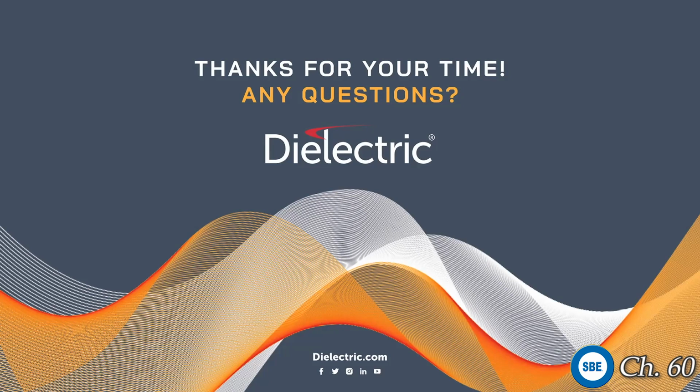Again, I hate to say it depends, but it really does depend on your scenario. Quite probably no. The only thing that you might need to look at adding is additional single frequency networks. As your footprint is pulling that power in closer to the antenna to boost that signal strength, by that nature you're going to be tucking that edge back in a little bit. And so in any of those areas that are low in received power, you're going to need an additional supplemental tower to fill that in. Thank you. Appreciate that. Yeah, absolutely.